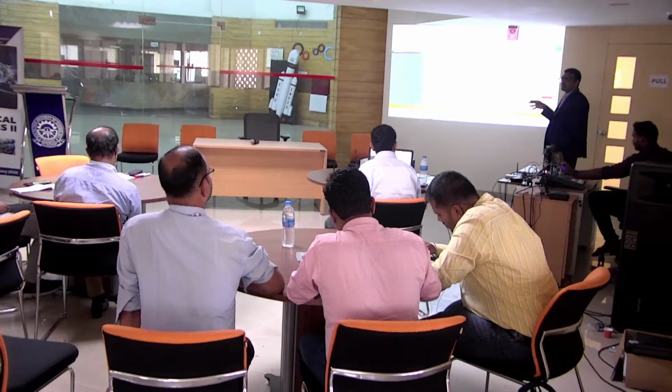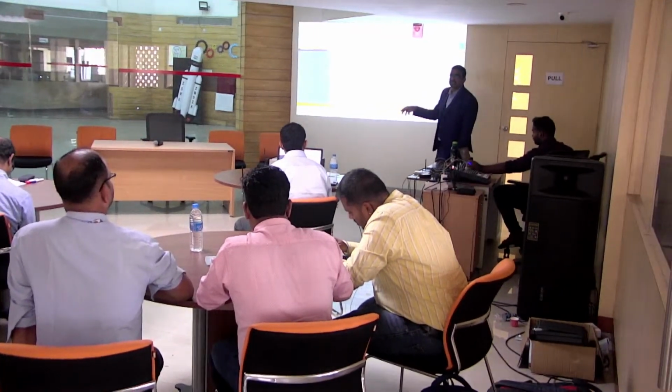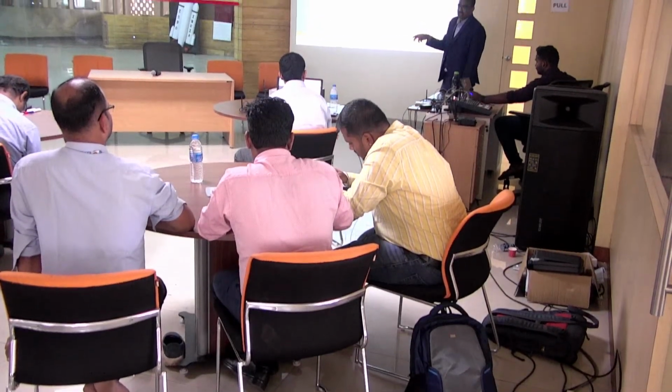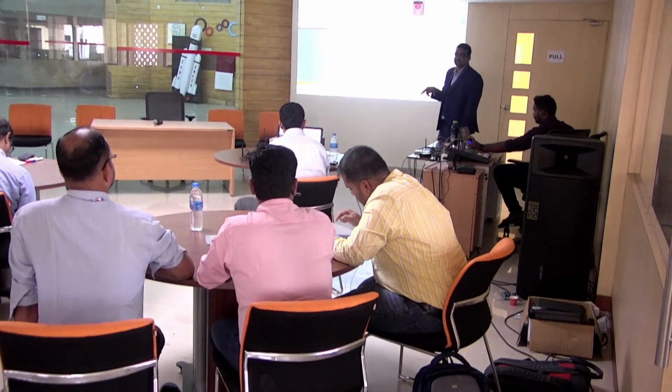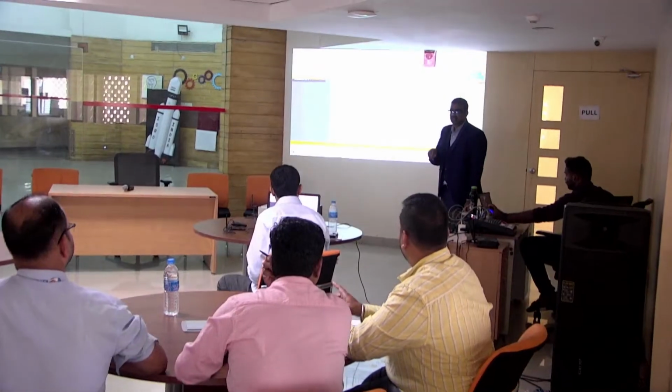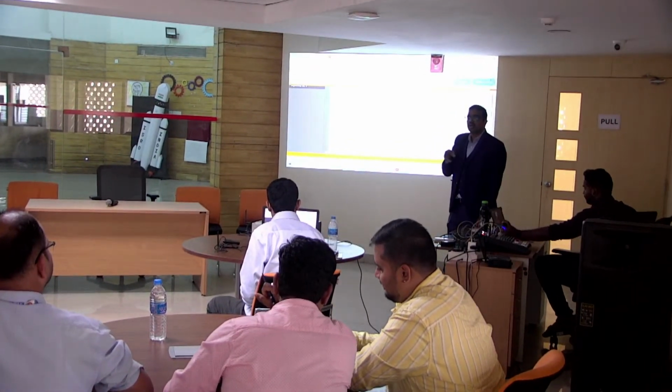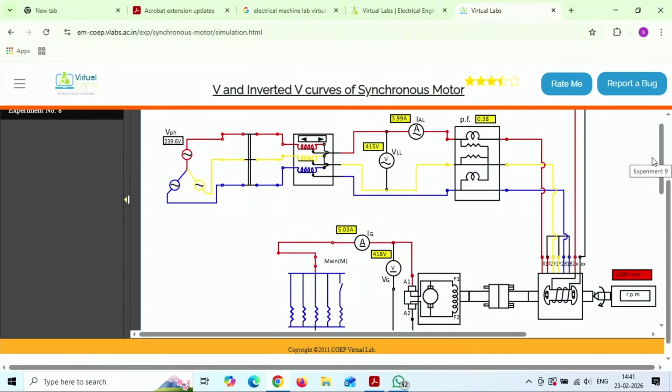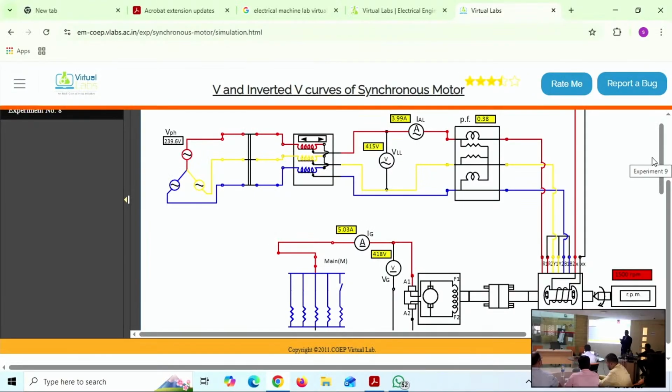So, the effect of over-excitation in the case of alternators, as we discussed, is purely demagnetizing, right? And it gives a lagging power factor, or otherwise it delivers reactive power into the system. We discussed this in the parallel operation of alternators and with the infinite bus bar, how the synchronizing power, under the over-excitation condition, is delivering reactive power.